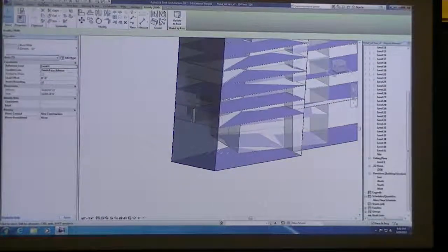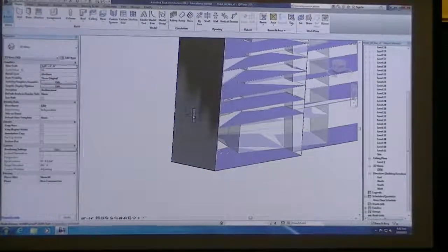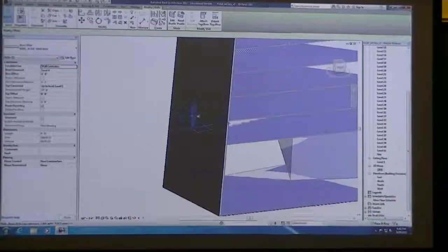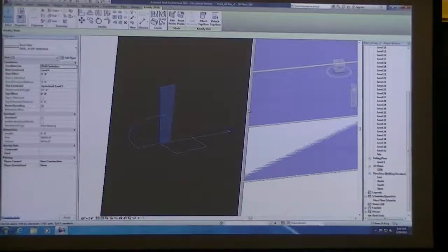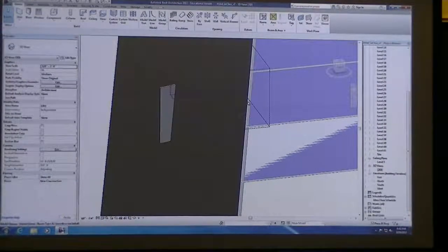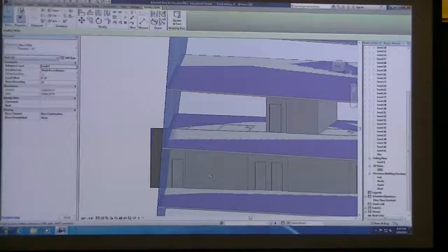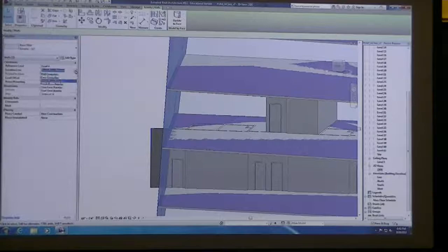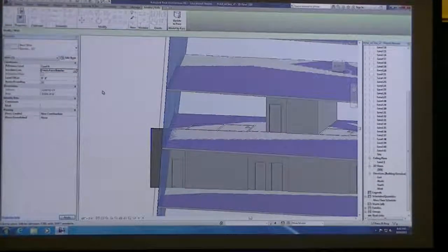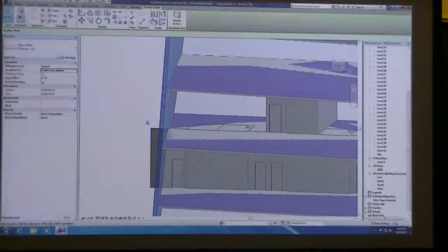And how did you split that again? Yeah. So by picking that wall, the first thing I wanted to do is make sure that my temporary wall that I've picked is moving outward instead of inward, so that I can really get that face and be able to snap to it. And the way I changed that was when you select that wall, under location line under properties, it says finished face exterior. I can place it by finished face interior, and it moves that wall out.